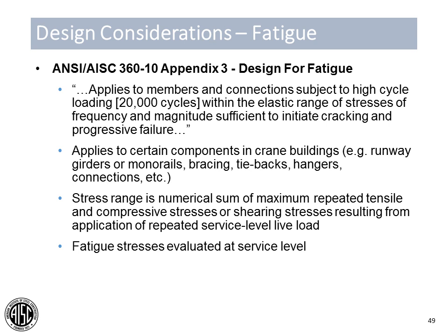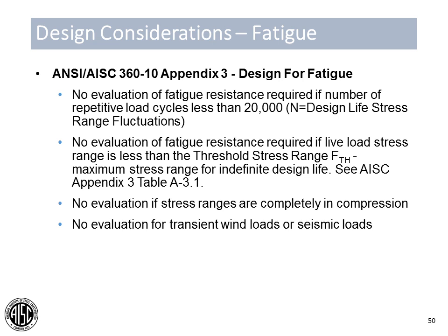It's the numerical sum, the difference between the maximum tensile and maximum compressive stress. The range is the full stress cycle that a specific point on a system will experience. And you would always evaluate these fatigue stresses at a service level.